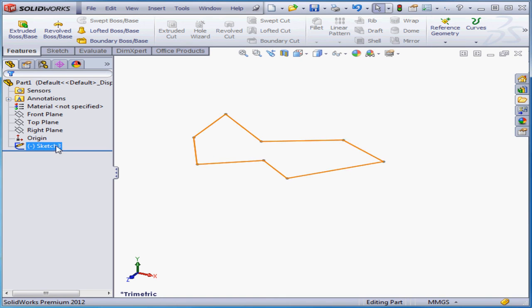Sketch 3 appears as a node in the design tree. And the minus sign next to the sketch tells us that the sketch is underdefined. In other words, the geometry doesn't have enough constraints, these being dimensions and relations, for SolidWorks to calculate a model as accurately as possible without moving it in space. Efficient and cleanly defined sketches are very important in the 3D CAD environment.